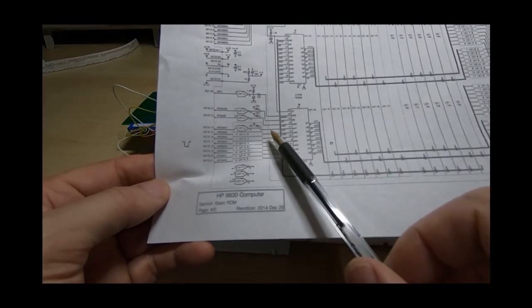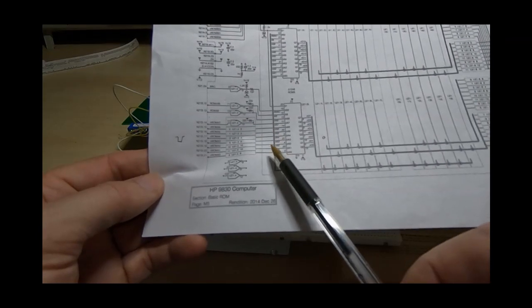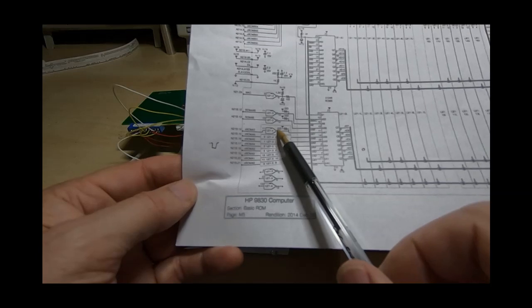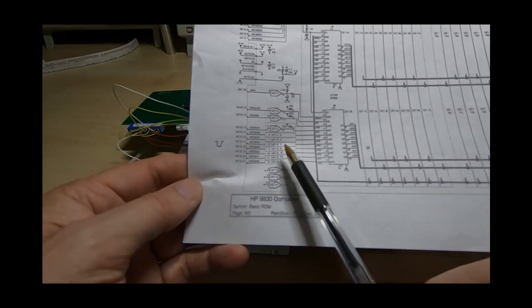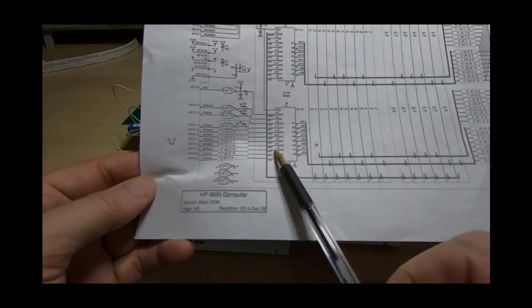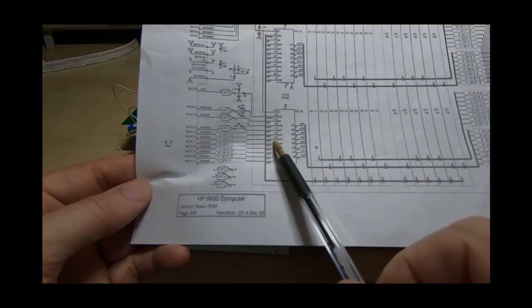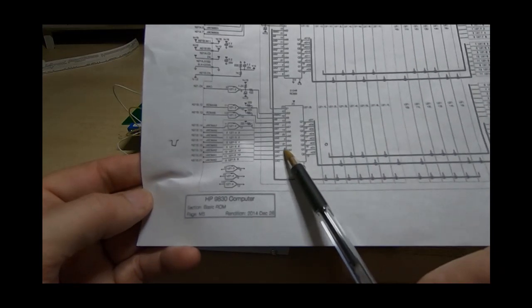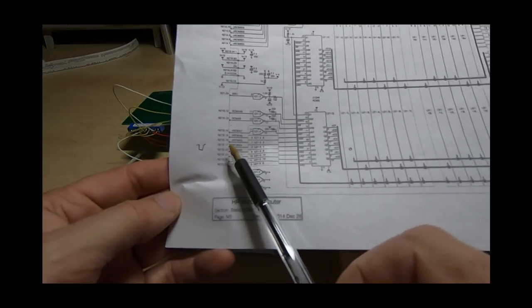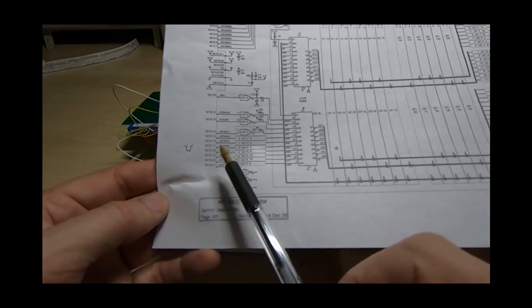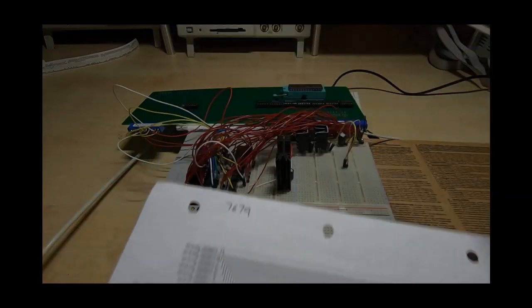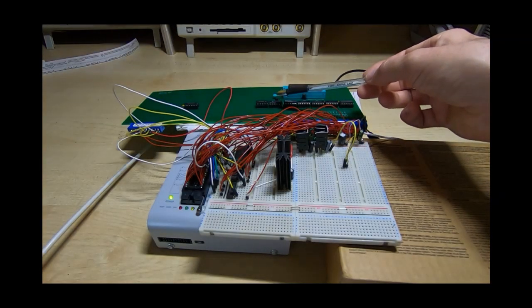Also, the lower 8 address lines are inverted. Although they're not really shown inverted here, if you look at the designations for the lines, they're shown as not address 4, not address 5, meaning that they are active low. This is because the lines are configured that way in the actual machine rather than it just being a requirement for the card. So that does mean that I've had to do the same with the card and that the